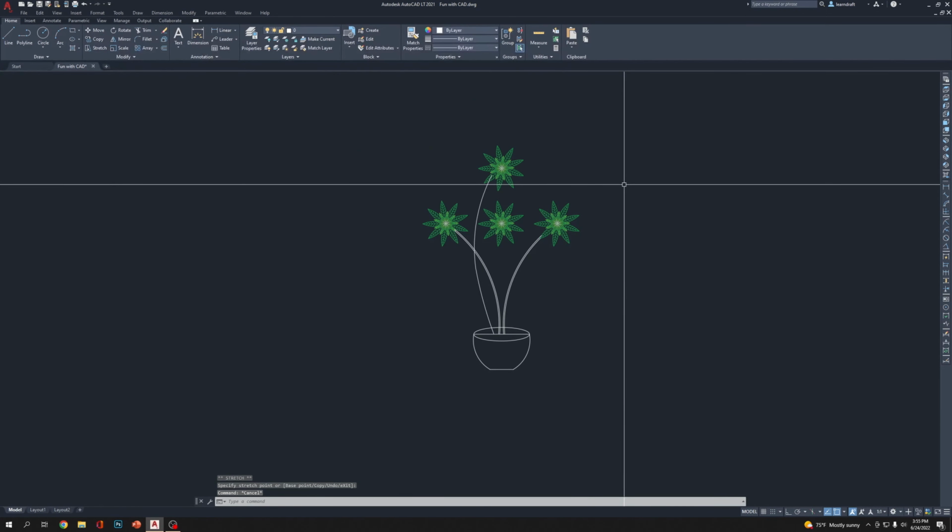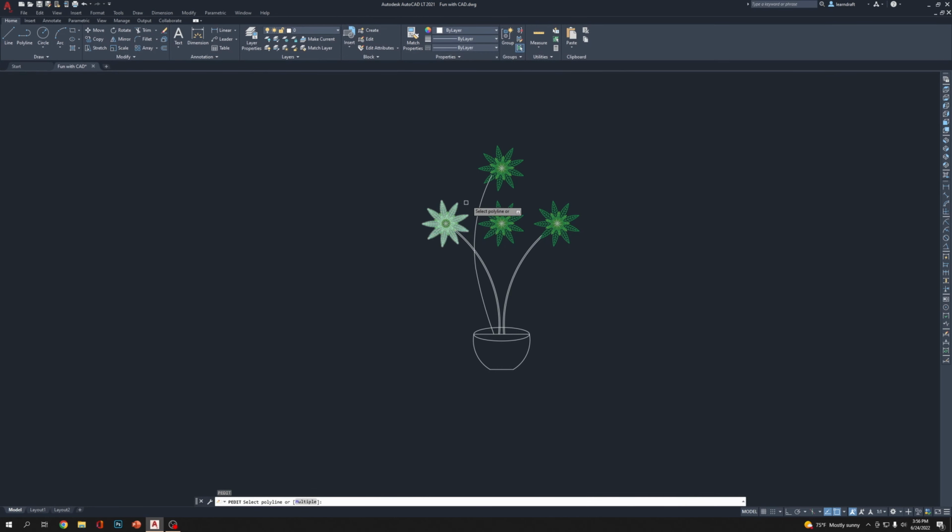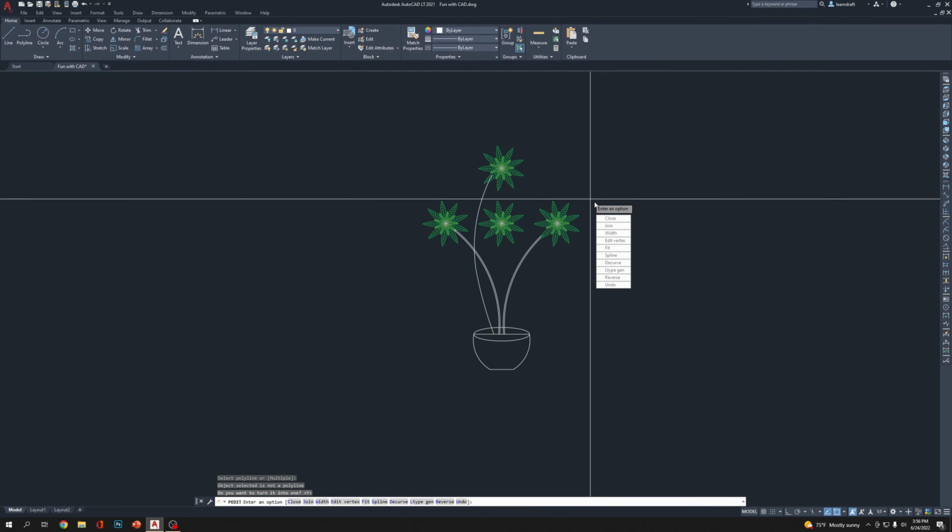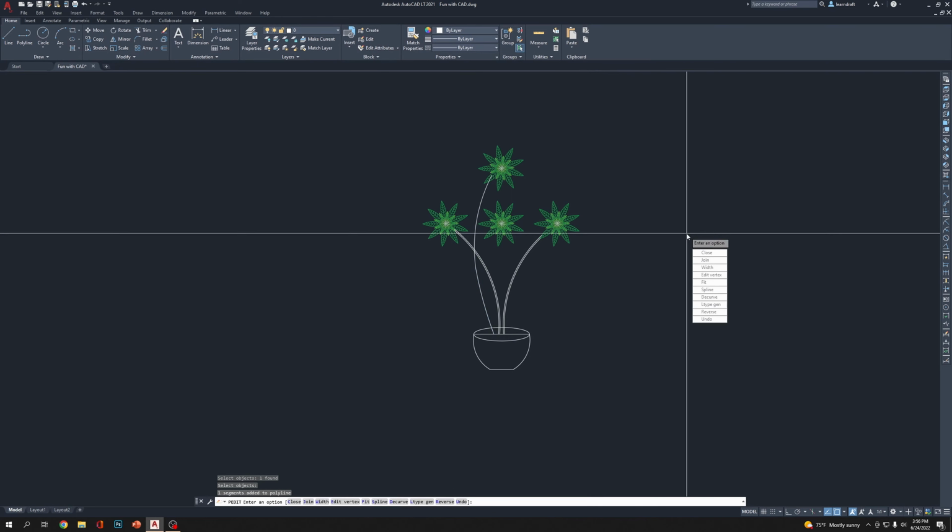Yes. So PE for poly edit, select this line, enter, join, select this line, enter.